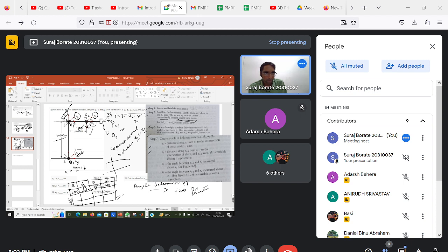Okay, to the intersection of x2 and z1. So x2 and z1 intersect over here. Okay, so what is the distance between these two? Is 40. Fine, so we can just write 40. Okay, d, what is d? D should be the distance along z1 from O1 to the intersection of x2 and z1.